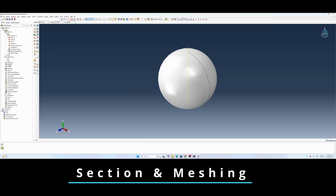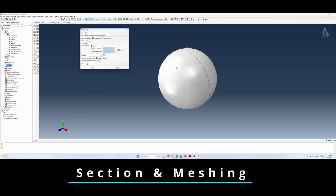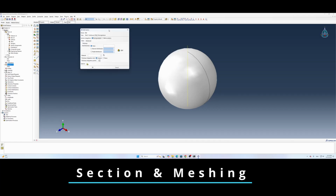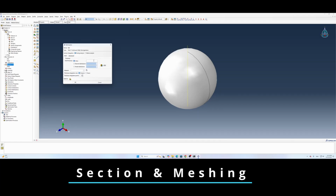And now we have to define a section for our parts. To do that, we go to the section here, double click. The name is going to be plate, shell, homogeneous, continue. And then for the value, I want my shell thickness on the plate to be 4 millimeters. And then the material is going to be my plate. Then OK, right click, create. And then the second one is for our ball. Again, shell, homogeneous, continue. For my ball, I want the thickness to be 1 millimeter thick. So the material is going to be our ball.